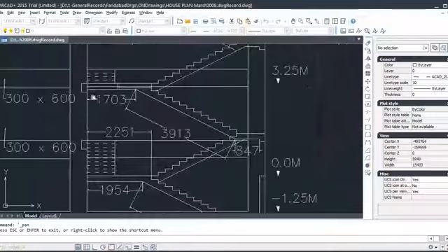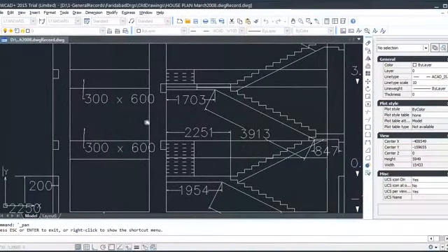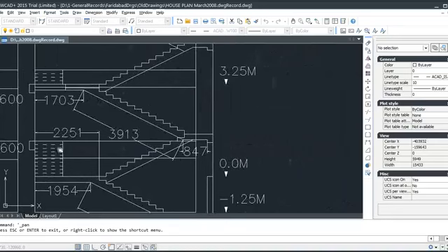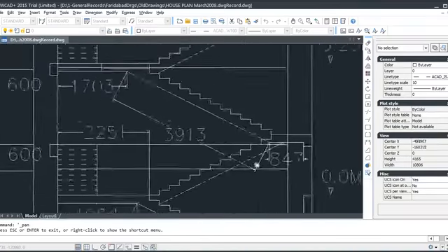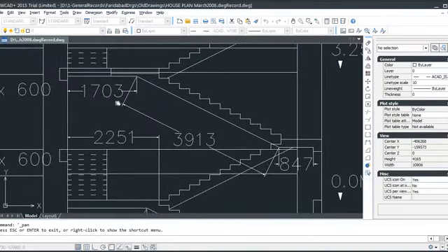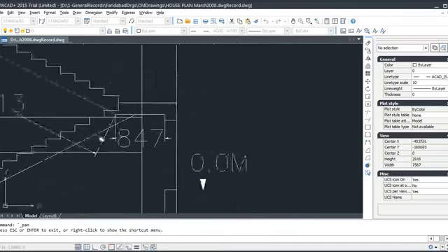And we show, for example, this beam here, and this beam here, and we show the dimensioning of this stair, how many meters from here this landing starts. Similarly, you can see the length of this shuttering, so that the carpenter can fix the shuttering here, and the size from the column to this, so that it would be easy for the carpenter or formwork to fix it. The carpenter need not use his own judgment. We give him dimensions, like we start here.